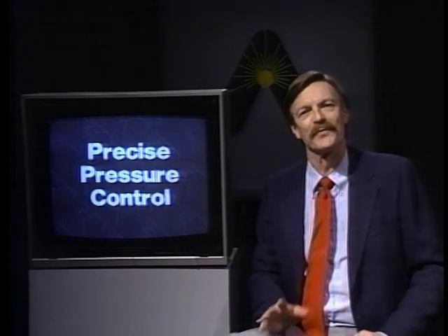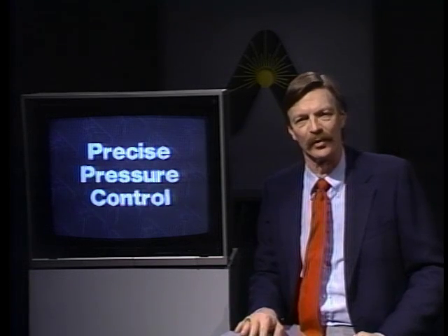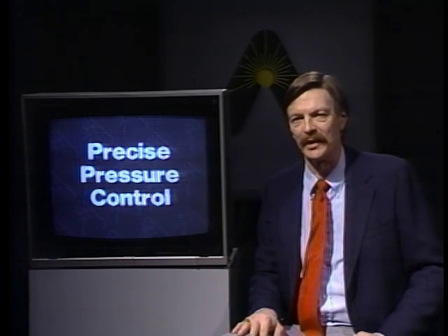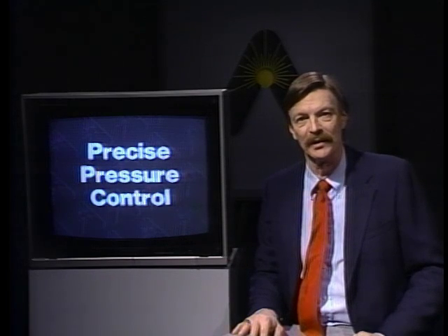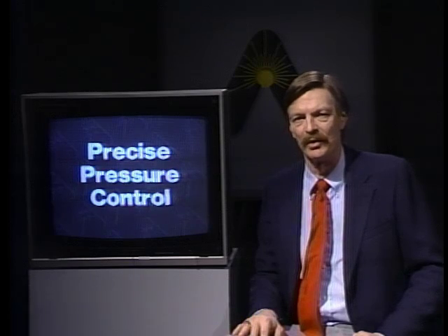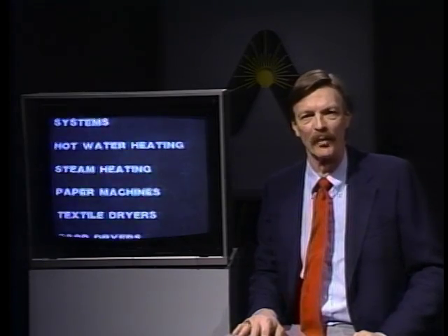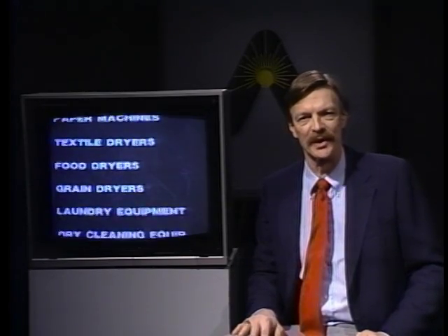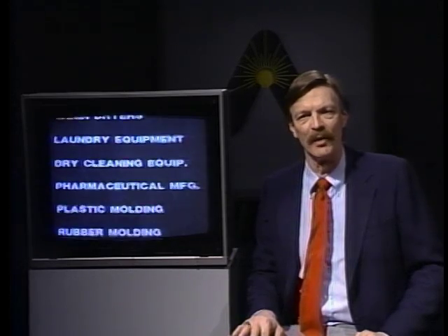There are several applications where these sorts of tight specifications are essential. Turbines, for example, need precise pressure control, accuracy of regulation in the order of 0.1%. Process heat exchangers often need pressure precisely reduced over a wide range of inputs. Most applications, however, have neither the performance nor power requirements to justify such systems. In the majority of instances, one of the several types of PRVs available will perform outstandingly.